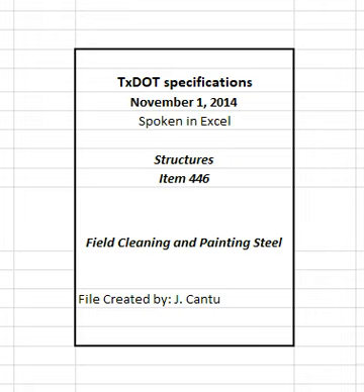4.7.4.5.3 System 1I. Prime coat. Apply 3.5 to 10.0 mils DFT of primer in at least 2 coats. Appearance coat. Apply 2.0 to 5.0 mils DFT of appearance coat. 4.7.4.5.4 System 1-2A. Prime coat. Apply at least 3.5 mils DFT of epoxy zinc primer. Stripe coat. Apply stripe coat of epoxy intermediate coating. Intermediate coat. Apply at least 2.0 mils DFT of epoxy intermediate coating. Appearance coat. Apply at least 2.0 mils DFT of appearance coating.